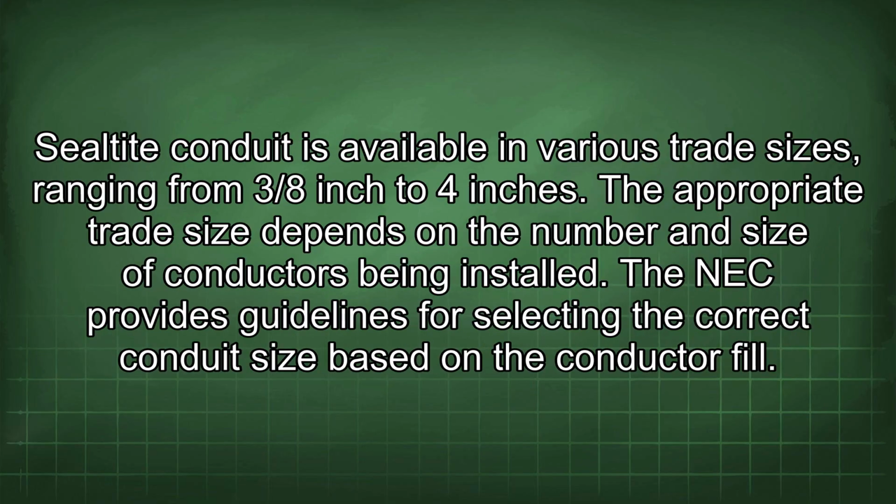Sealtite conduit is available in various trade sizes ranging from 3/8 inch to 4 inches. The appropriate trade size depends on the number and size of conductors being installed. The NEC provides guidelines for selecting the correct conduit size based on the conductor fill.